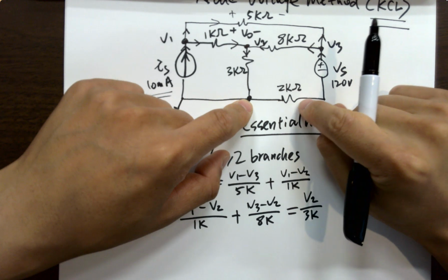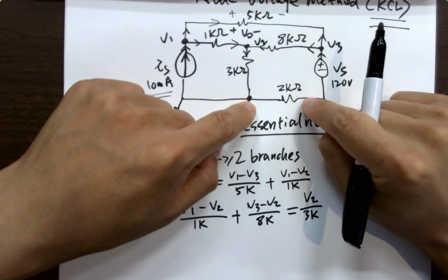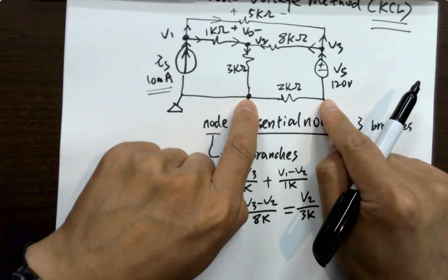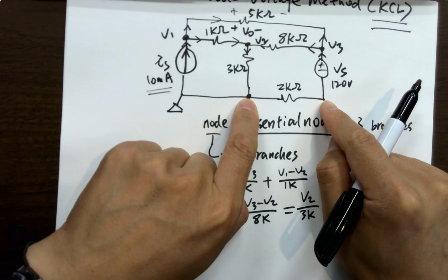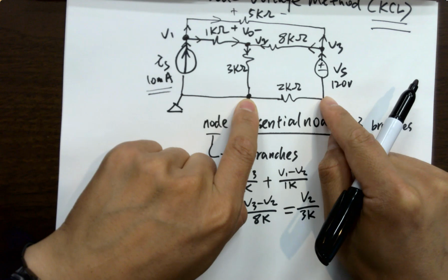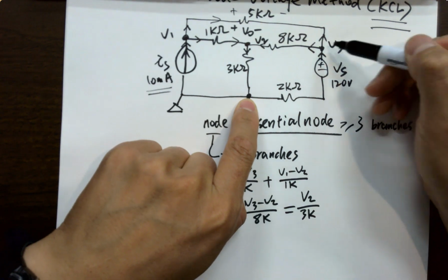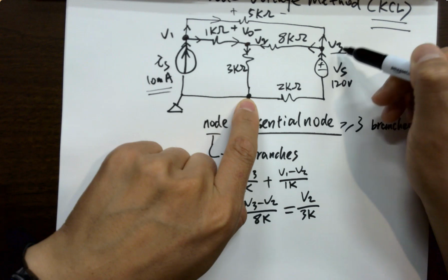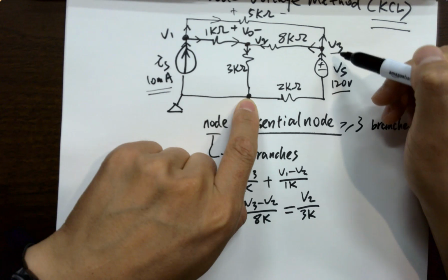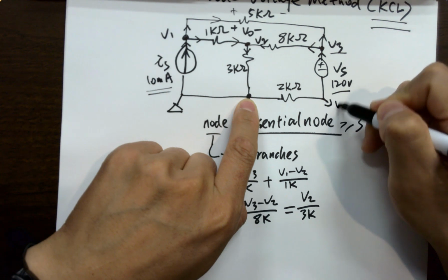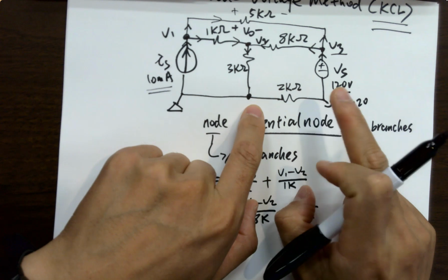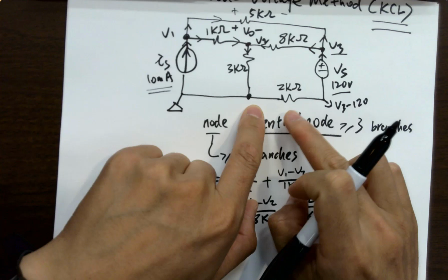Well, how can we find the voltage across it? We know the voltage here, do we? Yeah, it's 0, right? Do we know the voltage here? Not yet, but can we calculate it? We use a relative one. So it's relative. We already assume the voltage at this node is V3, right? And this battery is going to drop it by what? By 120 volts. So what's the voltage here, though? Yeah. So now we got a voltage across it, right? And then we can calculate the current.